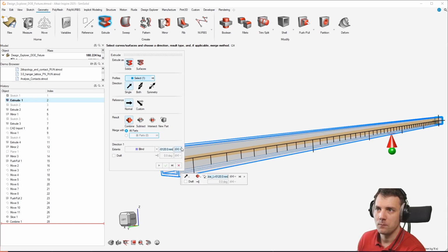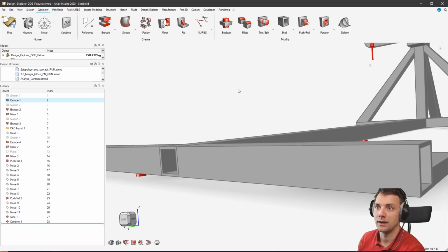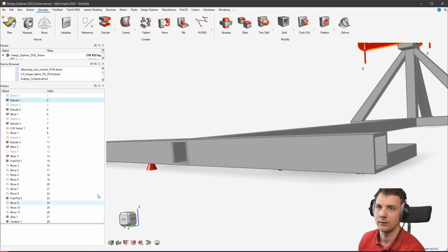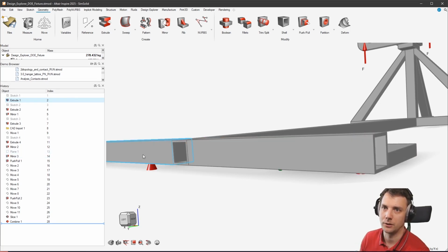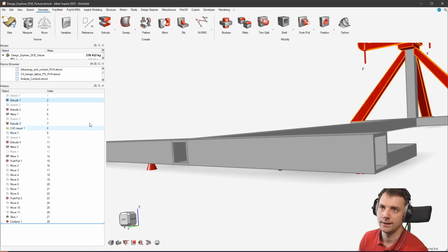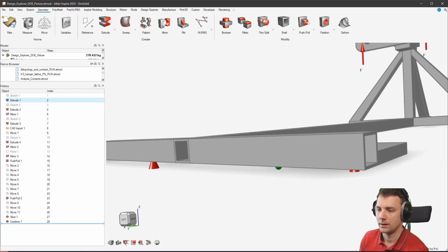So whenever you have a design variable, you can assign it here, and while doing that, this will then be added to this variables list, and so this is then being available. Okay, so F6 for the history, then you can go through what you did to create the geometry on this part, and then also add the variables at a later stage, right?